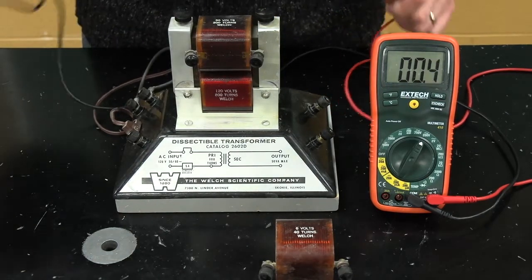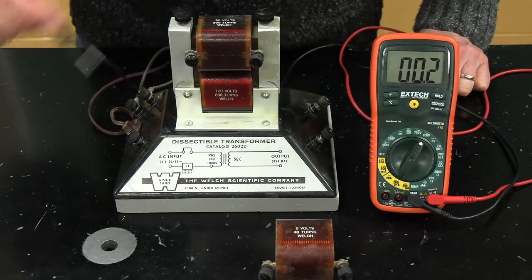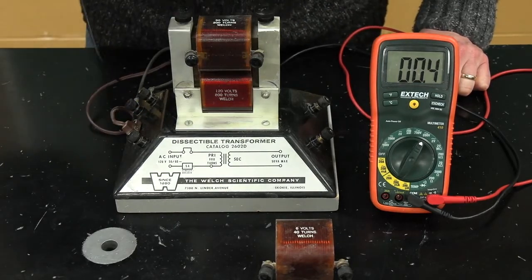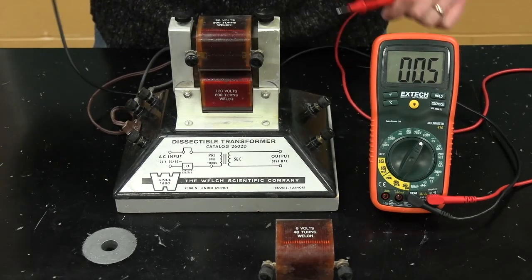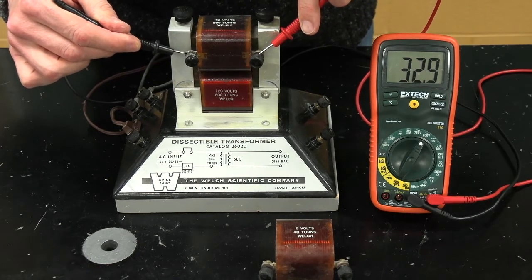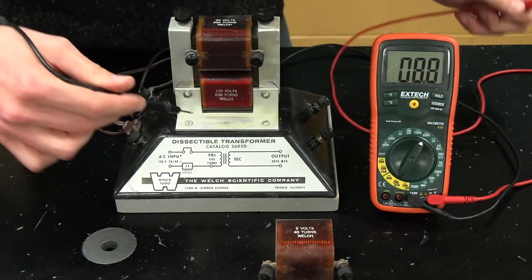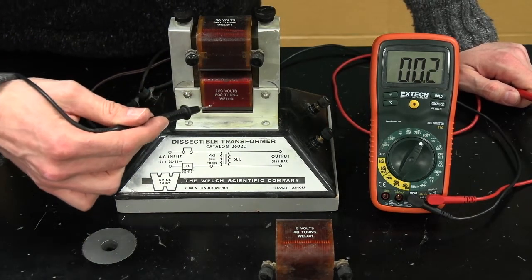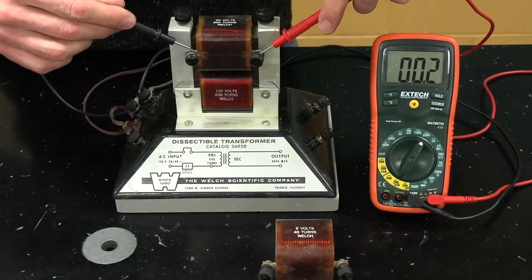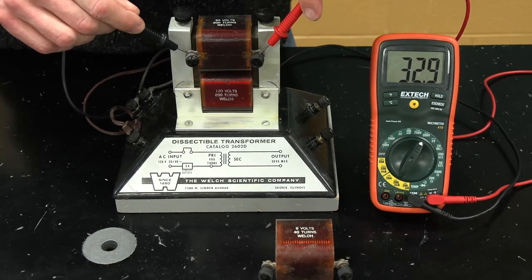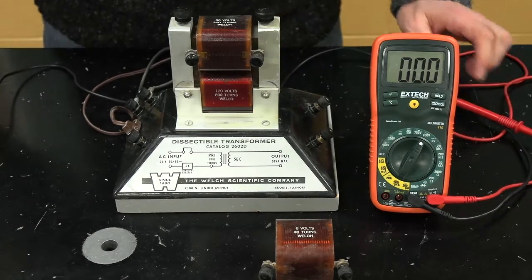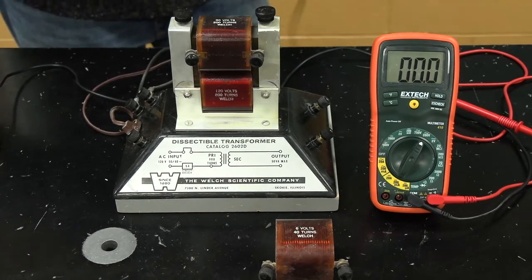Well, maybe I'll let you think about it for a moment. What do you suppose this voltage is? 800 turns, 200, 120 volts. This is, let's find out, 32. Well, about 30. Let's say 30 just to make it easy. So we had 120, 800 turns, and then we had 1/4 as many turns, and we get about 1/4 the voltage. 120 divided by 4 is about 30, what we got there. So that's what a transformer is.